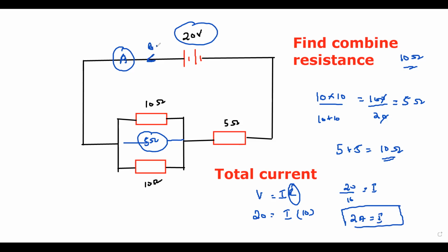So 2 ampere enters the circuit, the 2 ampere will flow. It will divide among these two branches, and then when it recombines it will be 2 ampere here and it will flow out. The same 2 ampere will return, but it will divide between the branches.